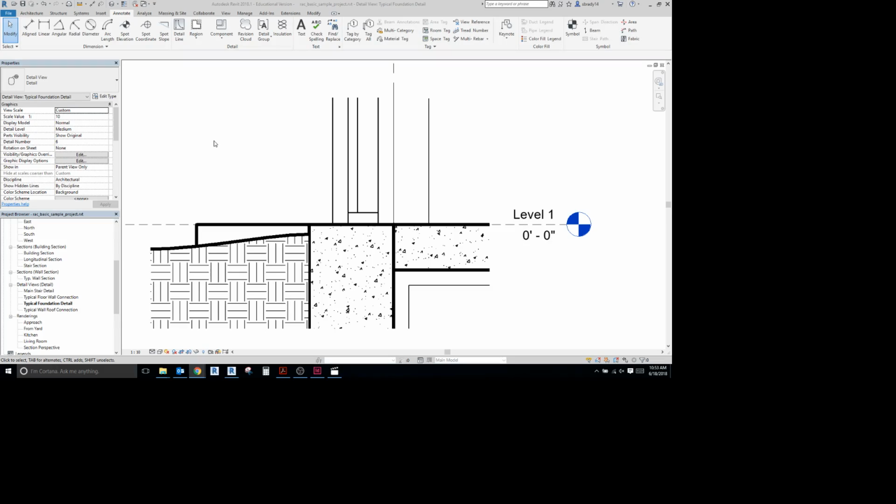Welcome to Section 4 of Chapter 15, Detail Components. We're going to use detail components in Revit to enhance our model geometry by providing construction details with more information on them. Detail components are Revit families that can be placed in drafting views or detail views or really any other view necessary to add additional information to the model. They offer a faster method of detailing than drawing individual detail lines.